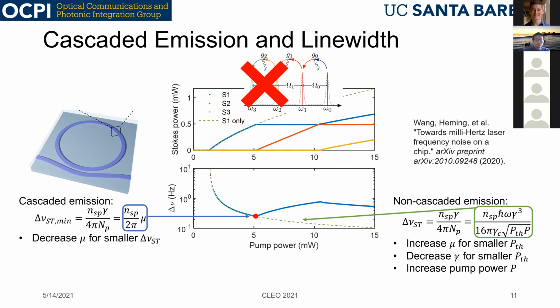In terms of how accurately we can control the silicon nitride thickness, for this work I think we deposited an additional layer of 5 nanometers of silicon nitride, so we talked with the cleanroom guys at Honeywell back and forth. We did several test runs for the oxidation of the silicon nitride thin film, and I do not have a number to describe the accuracy, but I think it's pretty accurate for them to deposit this 5 nanometer silicon nitride layer and then oxidize it, because we did the process development of it. I hope that answered the question. At least on the order of 0.1 nanometer, we could control that.